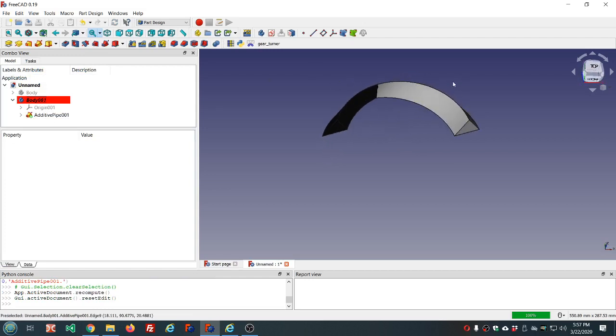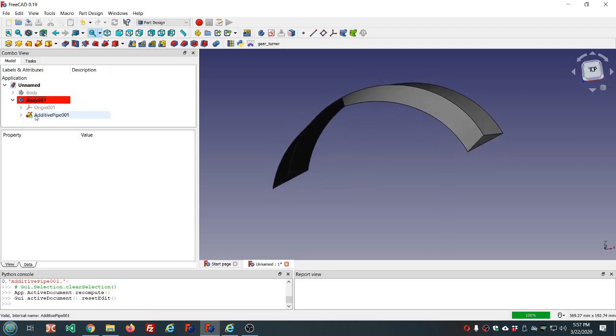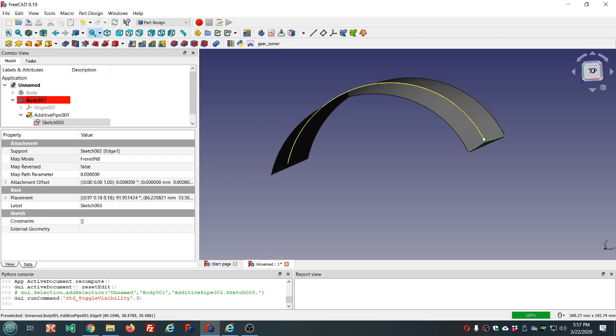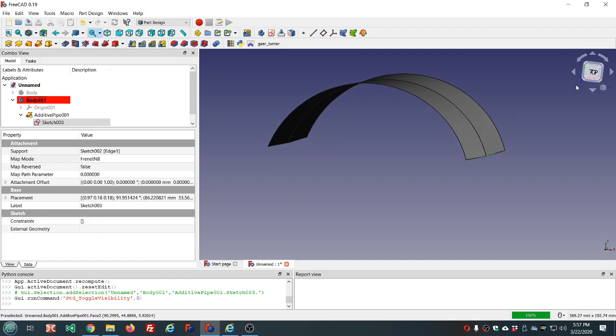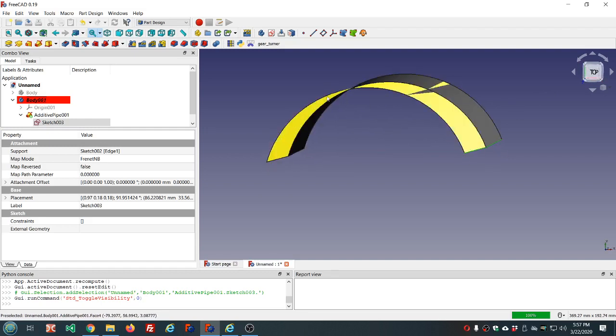So what does the fixed mode do different from the standard mode? The fixed mode has to do with the orientation of the profile. So as this sketch moves along, in standard mode, it remains normal to or perpendicular to the path. But in fixed mode, it doesn't change. It keeps its same orientation all the way through. And you get these self-intersections.